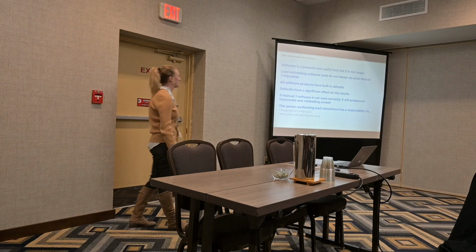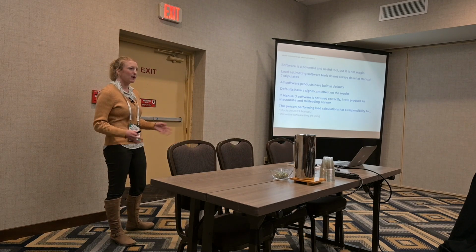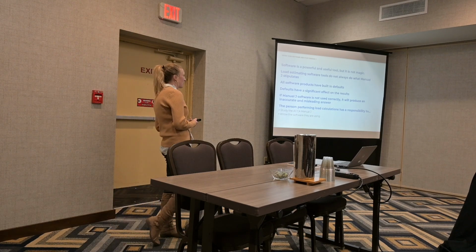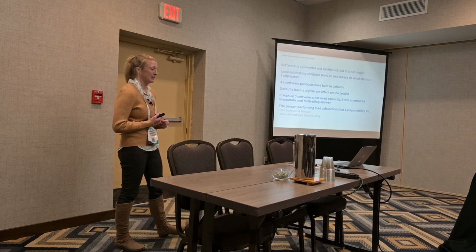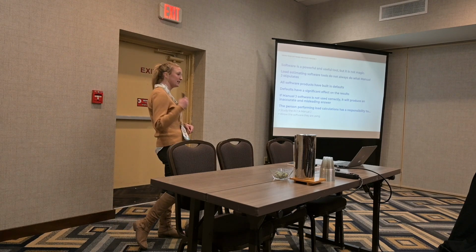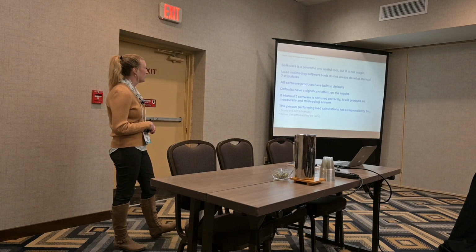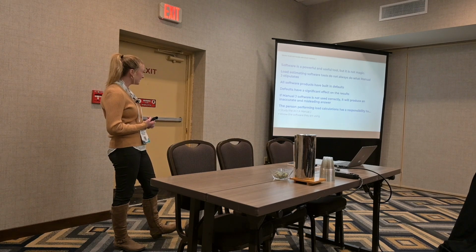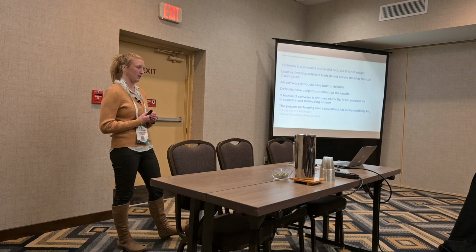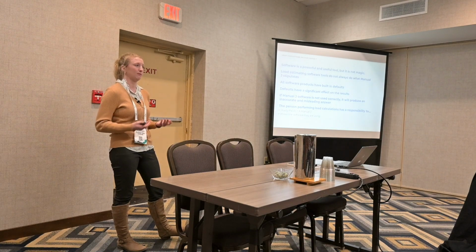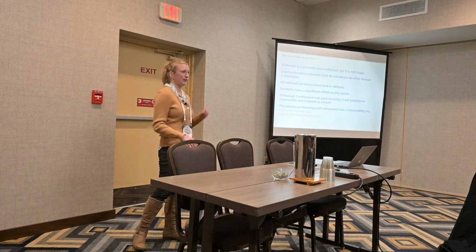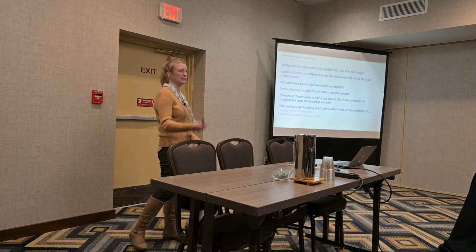All right, let's talk about software programs real quick. Software is a powerful and useful tool, but it is not magic. Load estimating software tools do not always do what Manual J stipulates. And all software products have built-in defaults, and those defaults can have a real impact on your results. So if you're not using Manual J software correctly, it can produce an inaccurate and misleading answer. So it's really important that whoever is doing load calculations has read through Manual J, understands it, and understands that the software they're using, and the inputs they put in, are going to come up with some built-in defaults.